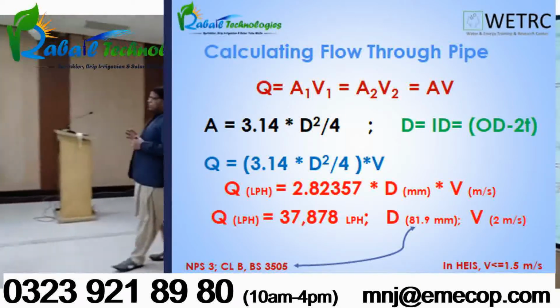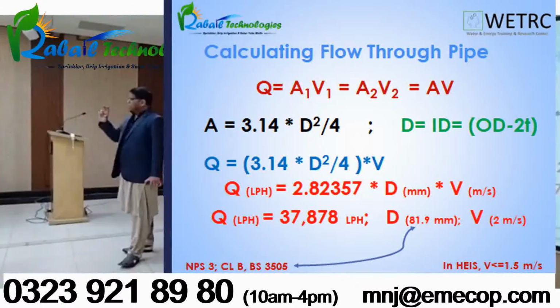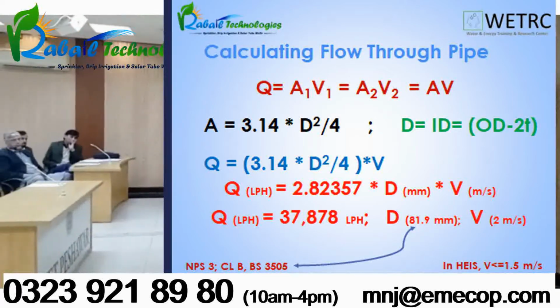Nominal pipe size means, for example, that the nominal pipe size is 3 inches. But if you analyze the 3-inch pipe, it will have an outer diameter of around 3.5 inches. So why do we call it 3 inches? Because it's nominal, a common way of speaking. What we commonly call 3 inches is, by the way, not actually 3 inches.